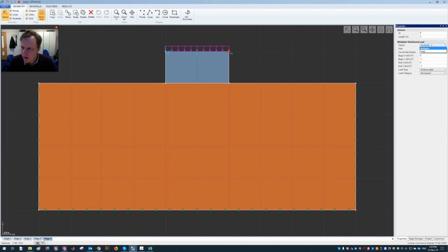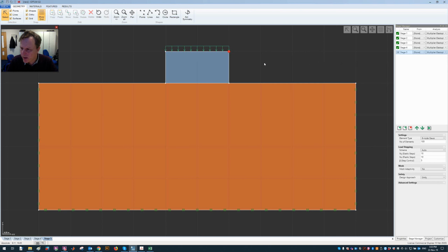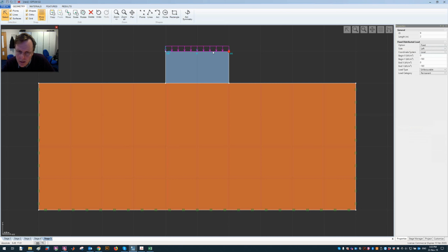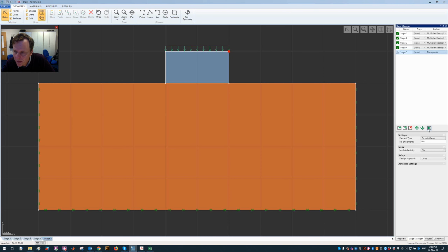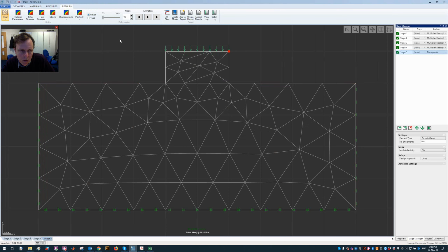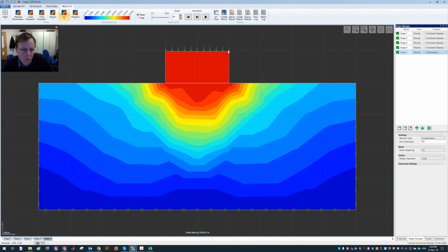And so if we change this instead to a fixed load and then went to something like, say, 100, and let's go 180, we could in principle run this as an elastoplastic analysis. So an elastoplastic analysis is an analysis where the load is not exactly incremented, the load is fixed. So we could apply this load of 180 kPa in one load step, and we can see how that goes. And we have a displacement up here of something a little less than what we had before. Of course, the load displacement curve is almost horizontal up at that level of loading.